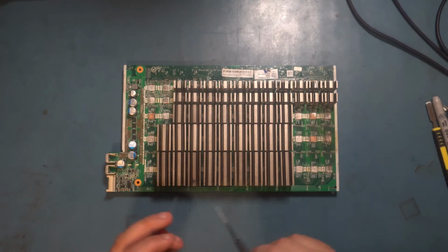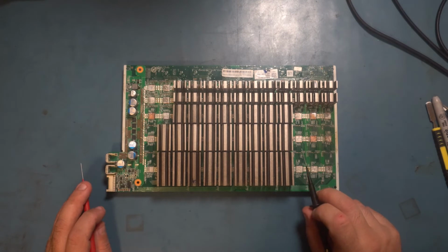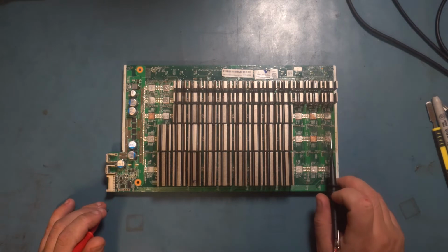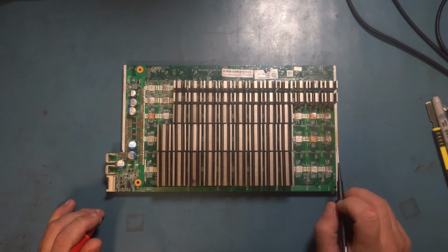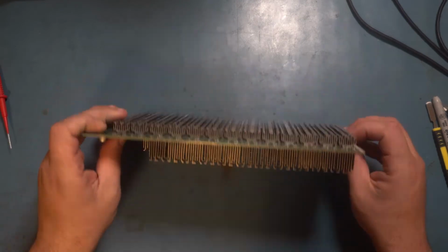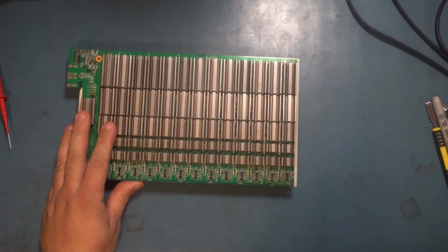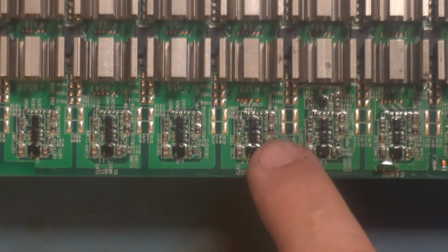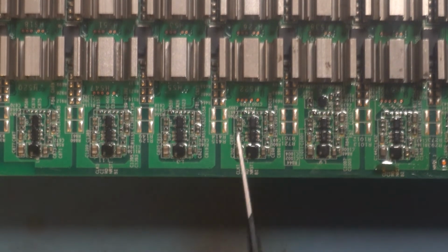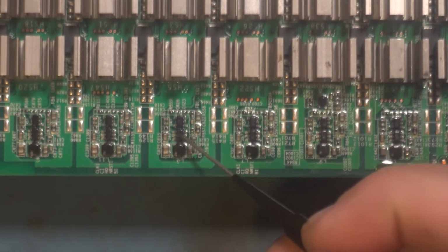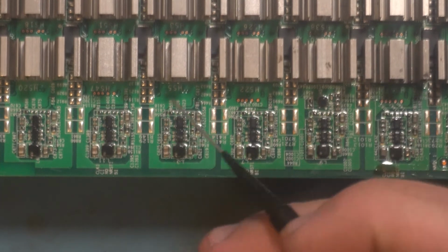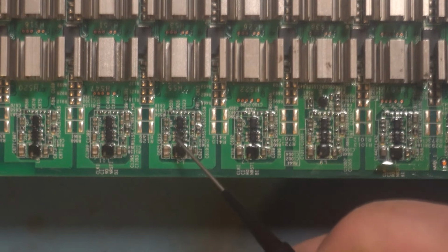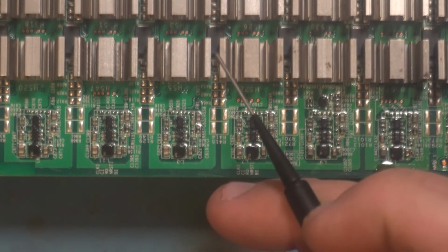But we also know that each domain needs a 1.8 volt and a 0.8 volt. And those are regulated down from another voltage through those regulators that are on the back, right? So every domain has 2 chips: one 1.8 volt regulator that takes a supply voltage of a certain value and regulates that down to 1.8 volt, and then that 1.8 volt feeds the chips.